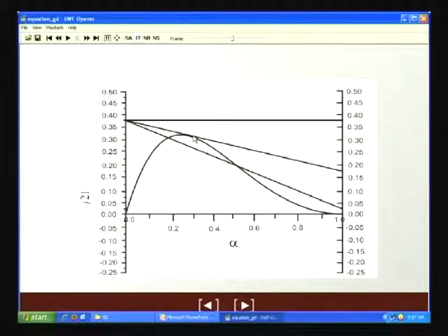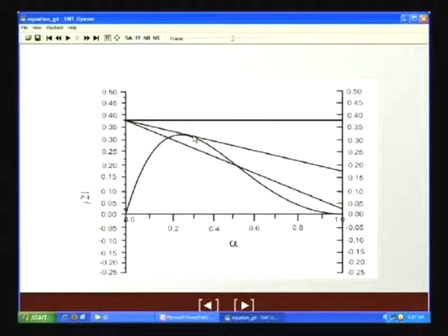What does it denote? It denotes the limit of counter current operation. When does the limit come? Under flooding conditions. Is it clear? So, therefore, this point of tangency gives you the flooding condition beyond which counter current operation is not possible.